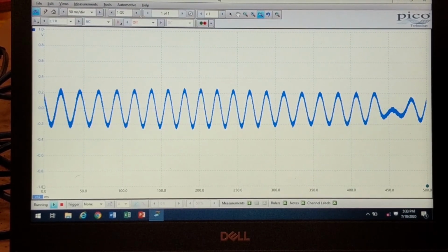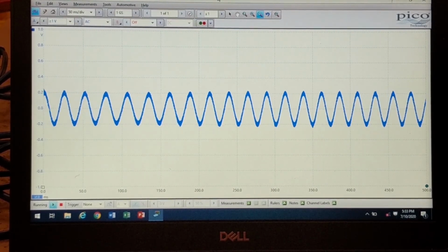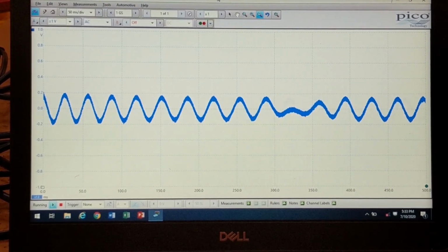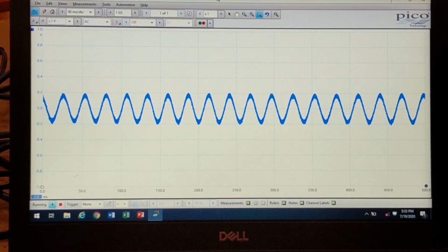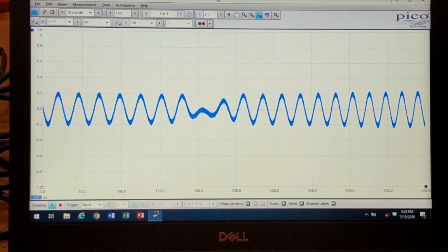You might notice that little hiccup or the squiggle in there. That's our fault. That's where the tone wheel has been ground down on one tooth. And you can see the effects of that. It doesn't maintain a uniform wheel speed sensor signal.